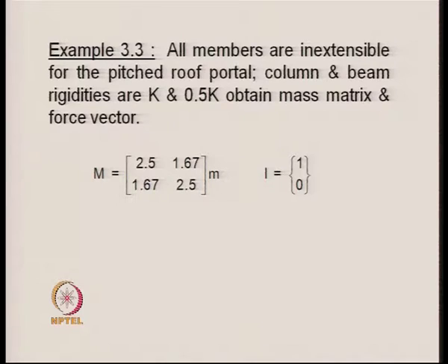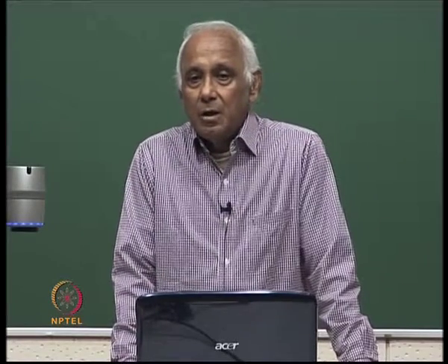Then we explained the equation of motion of a three-dimensional asymmetric frame with a rigid slab on the top of it. The idea was to illustrate that in writing down the equation of motion, the mass matrix need not always be a diagonal mass matrix, as is thought in the case of point mass lumping.